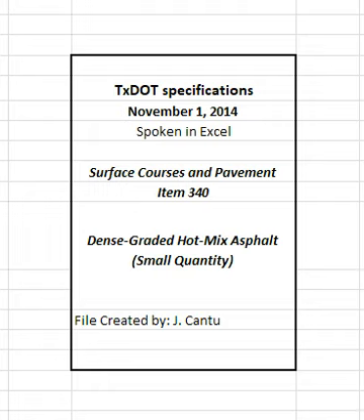If department-owned RAP is available for the contractor's use, the contractor may use contractor-owned fractionated RAP and replace it with an equal quantity of department-owned RAP. This allowance does not apply to a contractor using unfractionated RAP. Department-owned RAP generated through required work on the contract is available for the contractor's use when shown on the plans. Perform any necessary tests to ensure contractor or department-owned RAP is appropriate for use. The department will not perform any tests or assume any liability for the quality of the department-owned RAP unless otherwise shown on the plans. The contractor will retain ownership of RAP generated on the project when shown on the plans.